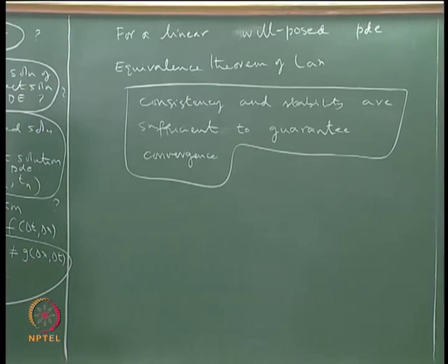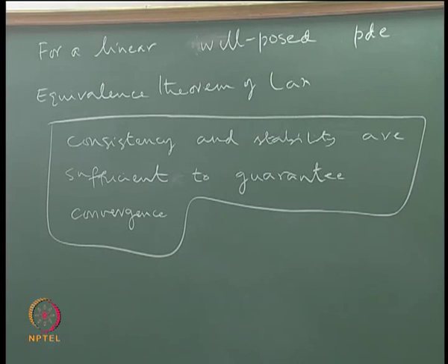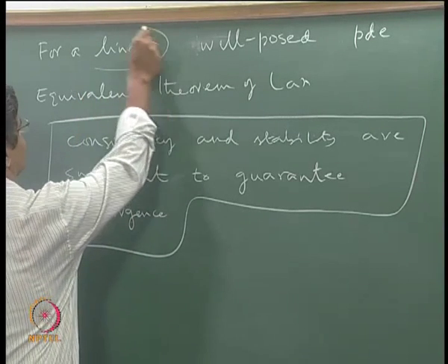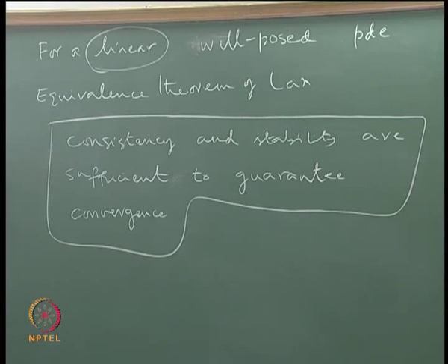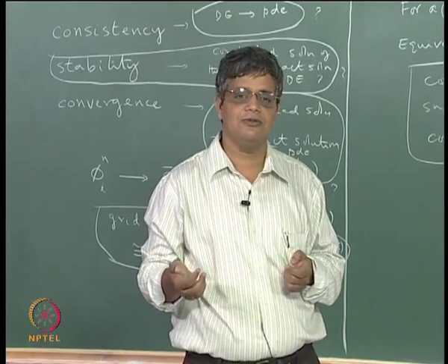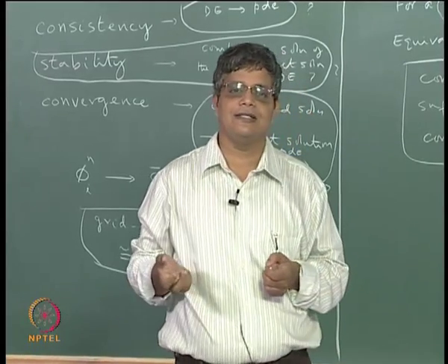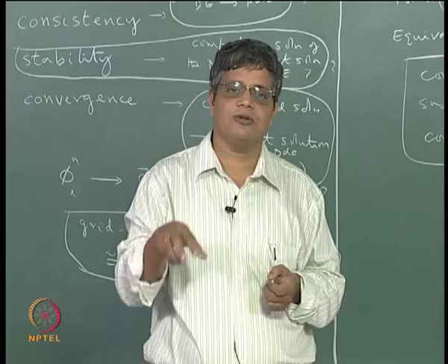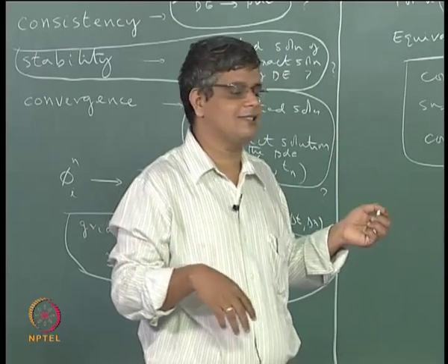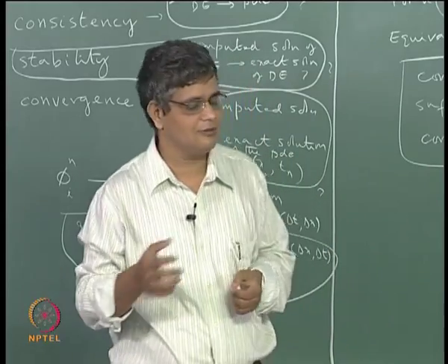but like all mathematical theorems it is also not of a great practical value from the fact that this is limited only to a linear equation. Okay, so when you have a linear partial differential equation, then this theorem works. For a nonlinear problem, which is what we normally have in our CFD, then this theorem does not work. Obviously it is only for linear thing, but in such a case we have to do local linearization. We can convert the nonlinear problem into a linear problem, and then for that linearized problem we can check for consistency using this. So in that sense it